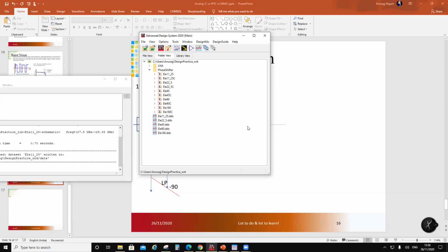So even if you want one more element, you can stop at 11.25 using circuit elements, and then just use a transmission line to get the other bits. But according to me, if you go 5.625 and below, this will not result in any system accuracy on a phased array. So 5-bit is good enough for most of the applications.